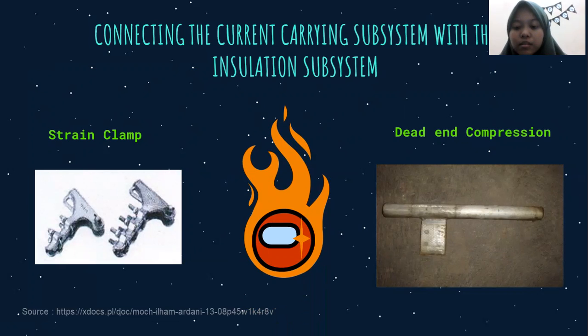So based on its role as a supporting component, the junction is divided into A, connecting the current carrying subsystem with the insulation subsystem, which consists of a strain clamp. A strain clamp is a device that is attached to the conductor to tension insulation equipment, which serves to hold the conductor on the tension tower.